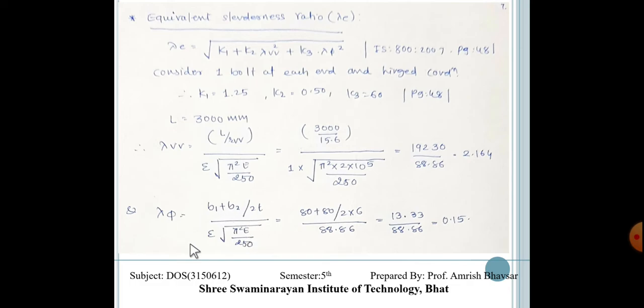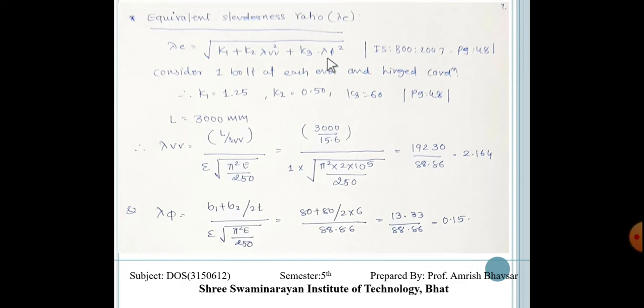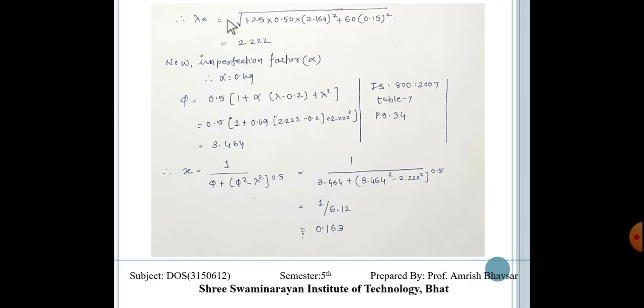After putting k1 and k2 we get lambda phi, that is 13.33 upon 88.86, which is 0.15. Now we have these values; putting all five values in this equation, we get the effective slenderness ratio for our section, that is 2.222.